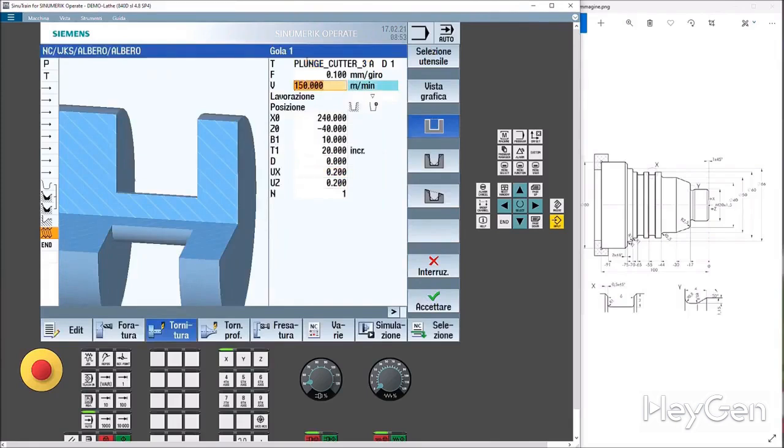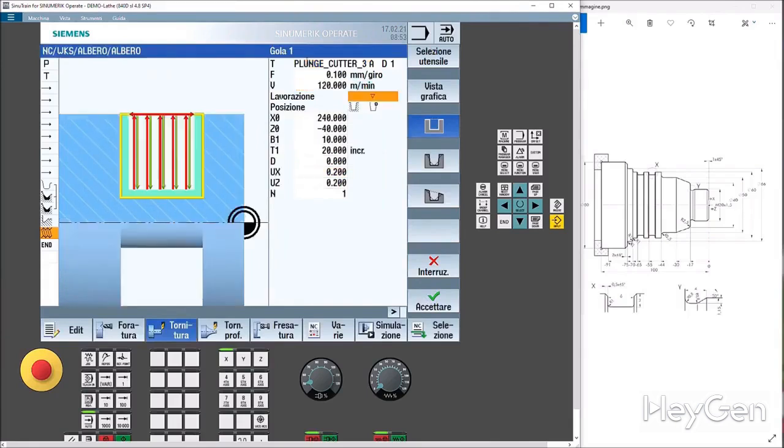That's more than enough, 120 meters. Today, I haven't worried too much about the material we're working with and the parameters. So, when machining grooves, we rough them out and finish them only in special cases. We change the tool when we have a specific groove bottom position.